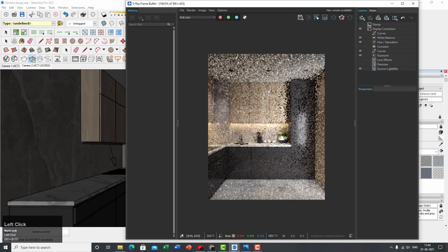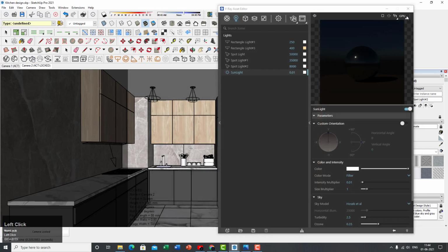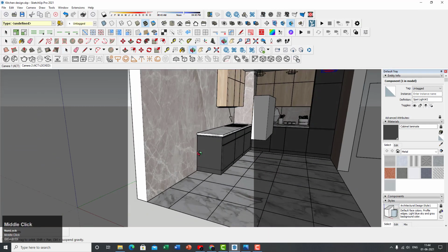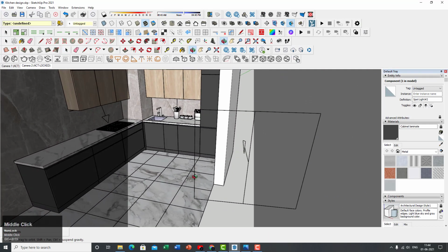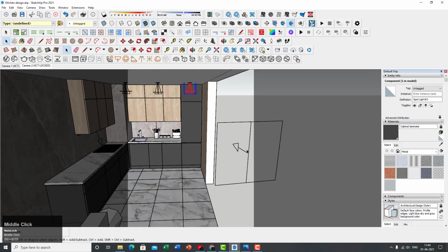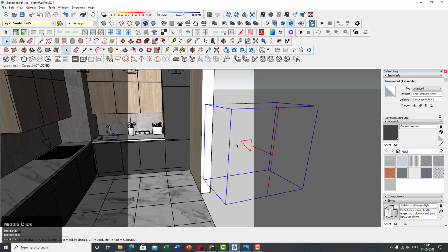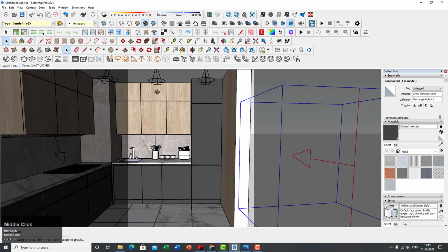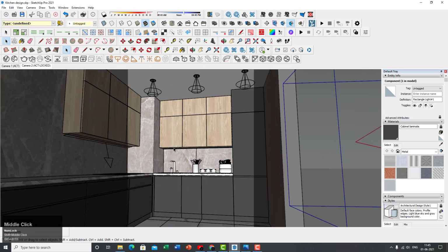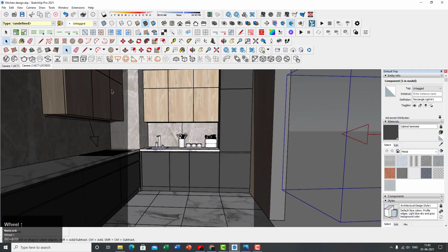So if I click on the interactive render, this is what it gives you over here. So this is how I set it up, and let me show you in my scene how I have set up my lights over here. Eventually I rotated my rectangular light to about here to match the original picture. This is the size I actually went with, and I put it outside, just ever so slightly inside the room. And these lights should be looking like this in your model. So these are the lights I basically use for the entire model and nothing else, to be honest. So if I go back to my camera view